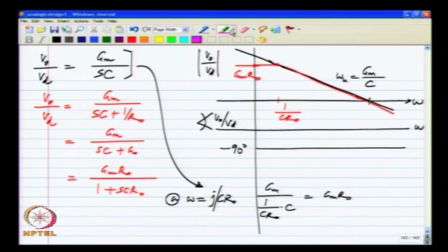So, at this particular frequency even the integrator has the same gain. So, in the Bode plot sense, the red line meets the black line and then follows the black line, because after that the slope is 20 dB per decade for both of these curves. So, this also means that even this one intersects the unity at a frequency approximately Gm by C.